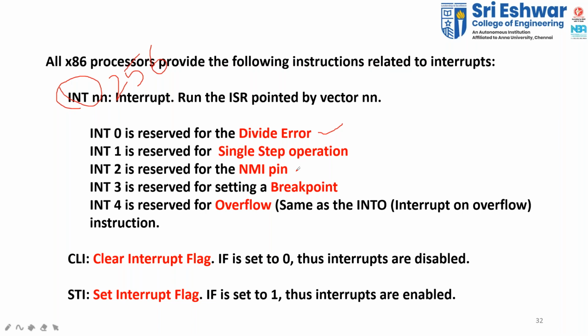What happened to the results? Whether we have overflow or parity or zero or sign, these are all taken into consideration. It shows the status of the microprocessor. So I should clear this flag register, or I should set and reset it, right? Setting a flag is nothing but giving 1 to my flag. Resetting a flag is giving 0 to the flag register, that is, enabling the flag, disabling the flag.